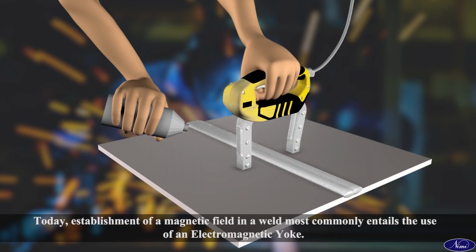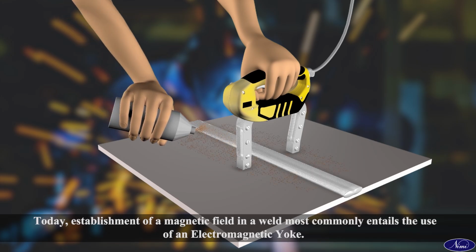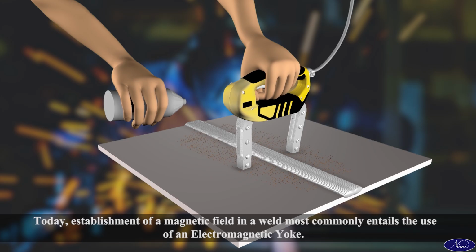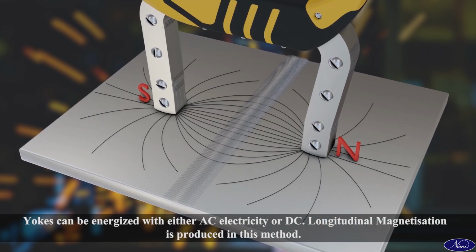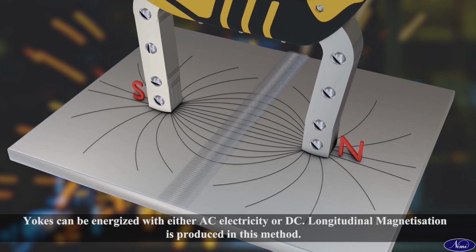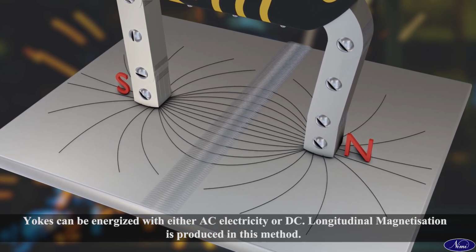Today, establishment of a magnetic field in a weld most commonly entails the use of an electromagnetic yoke. Yokes can be energized with either AC electricity or DC. Longitudinal magnetization is produced in this method.